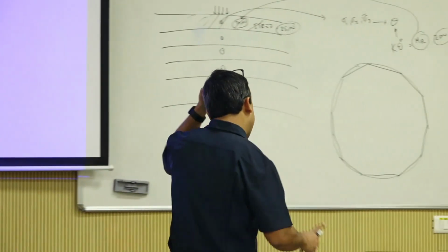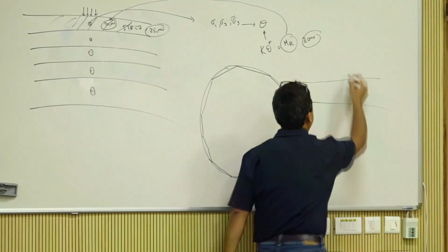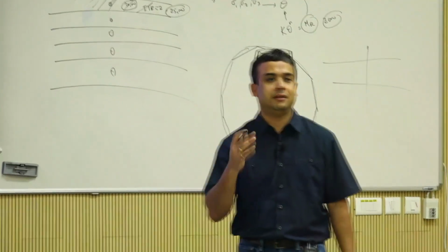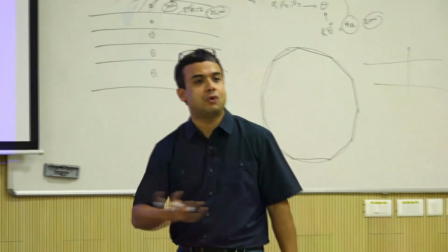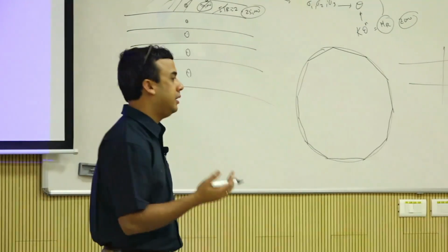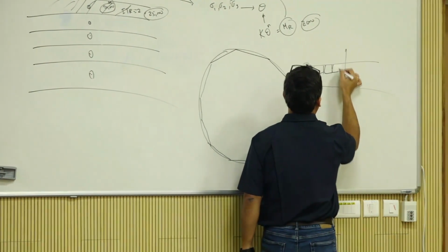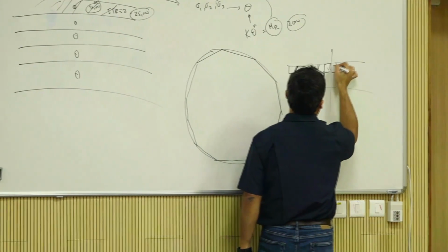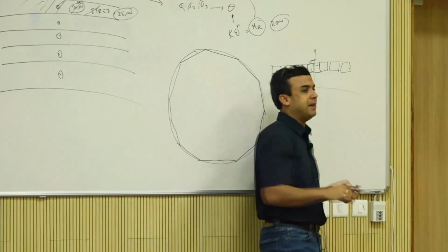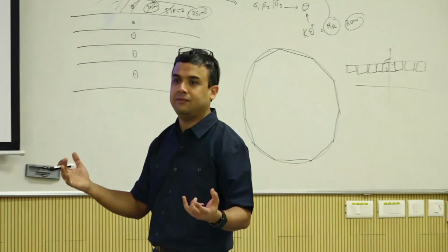Does that mean when I have a pavement for you, and I have a crack over here or a slab over here, a joint, and you're like, man, my layered elastic theory is not going to work because it talks about semi-infinite elastic space and stuff like that. What am I going to do, right? You're like, okay, let's not worry about it. We're going to talk about very small elements, and when we come here, we're going to change some properties here and whatnot to capture that. Other than that, everywhere else it's going to be the same, and I'm going to assemble the entire system together, right? Then make an inference about this.